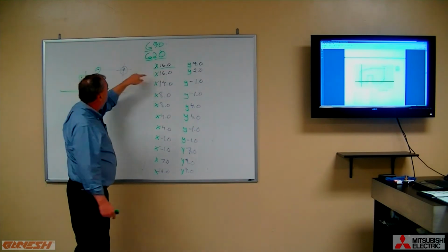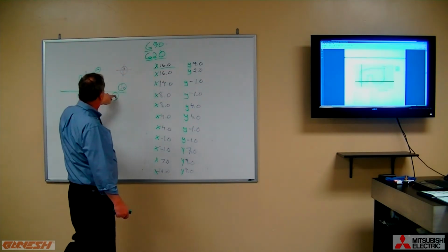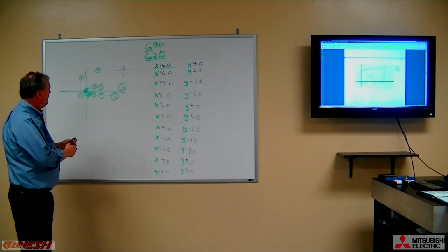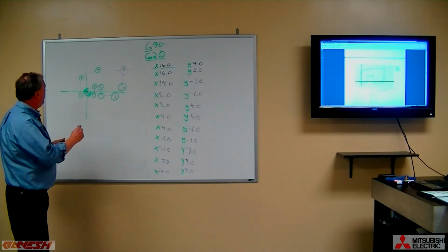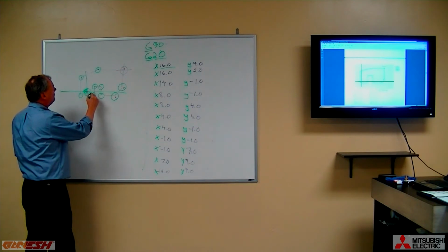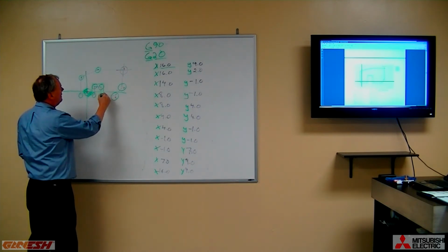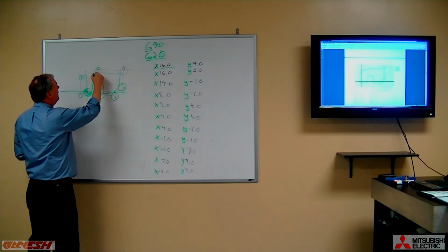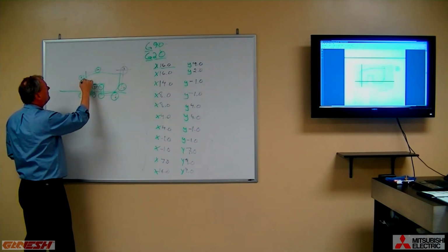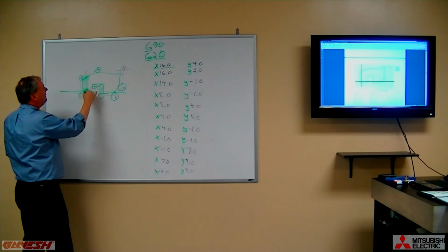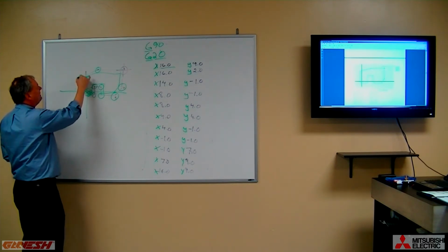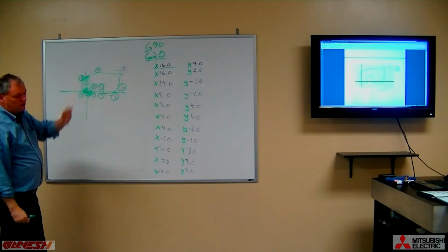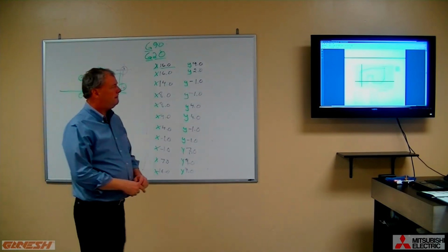Know that these numbers always are the center of your spindle and not the edge of a tool. So in reality, what would our finished part look like? Well, the cutter will have gone around, so the part will actually be smaller by the diameter of the cutter. And this will come to light a little bit later.